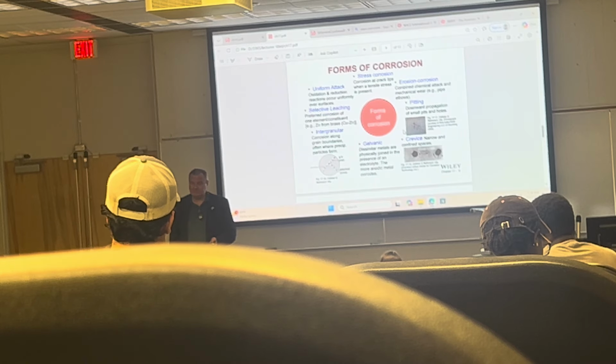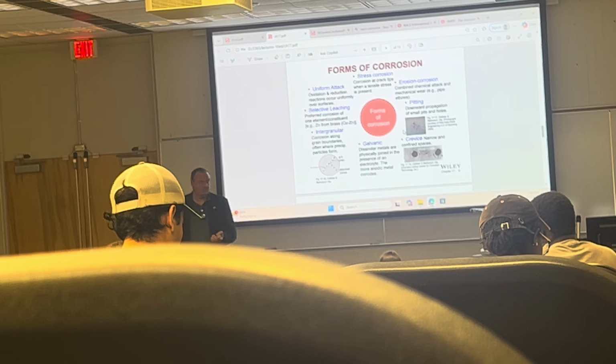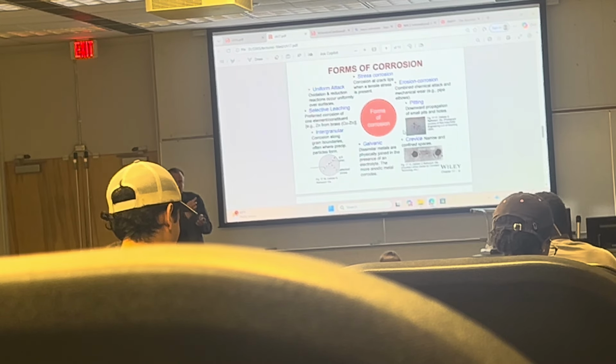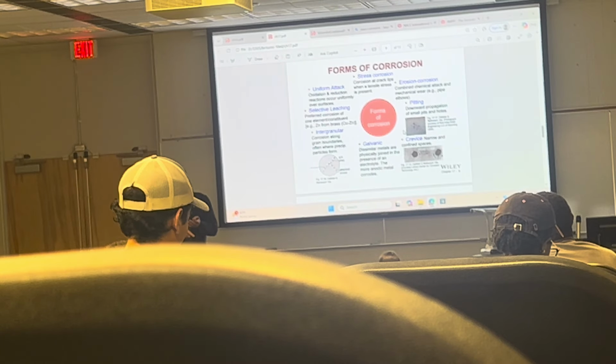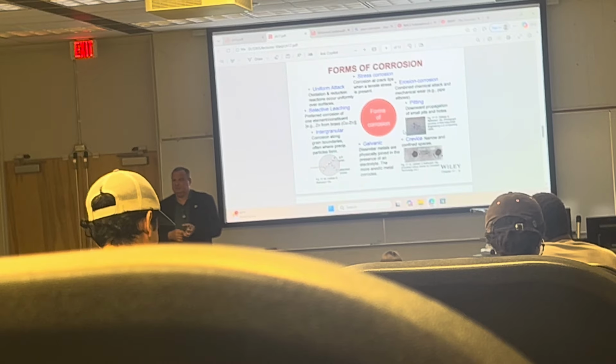It's not supposed to rust. But does it? The mechanism of corrosion of stainless steel is different. So you're not getting uniform attack, but you get pitting corrosion. And pitting corrosion is very dangerous because it happens in a very small localized area and you end up with a hole. And inspection does not always allow you to see it.